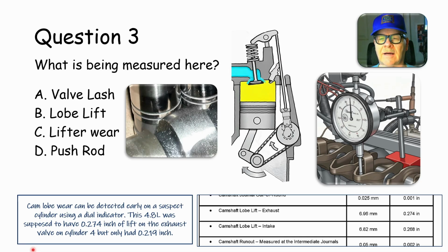A lot of times we won't pick up on a camshaft that's rounded off until it starts popping back through the intake like a machine gun, or making a lot more noise than this one was making. But just driving this vehicle, even doing a volumetric efficiency test, I really didn't see much of anything I could detect. It was because of Jonathan's sharp ears that he heard the hydraulic lifter was having trouble maintaining the proper lash.